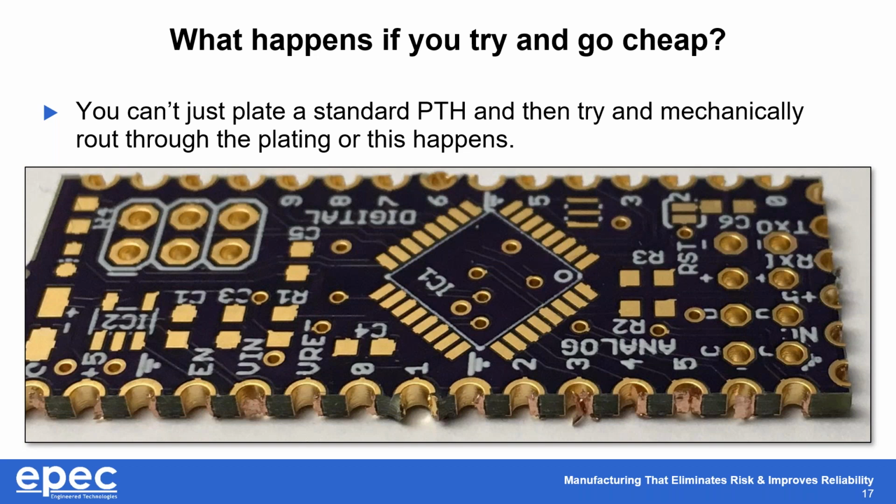And it creates huge problems because when you do that, you're loosening the copper plating from the hole itself. And so while it may look like it is there and it is absolutely not going to be a problem, a lot of times during soldering, you'll find that those little slivers will come off, and then you'll find them attaching themselves to other features on this module and creating shorts. So it's really important that as a customer, you identify what is acceptable to you so you don't get this.